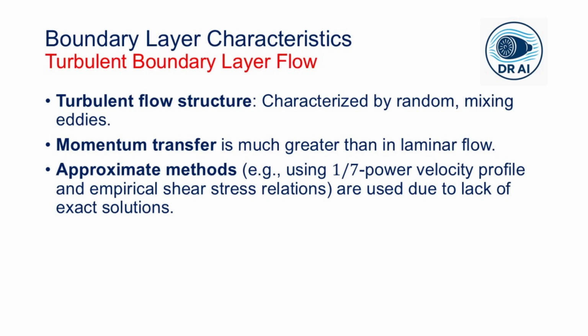Fluid particles moving towards the plate carry excess momentum from regions of higher velocity. Particles moving away from the plate gain momentum from the fluid. So this random cross-stream transport extracts momentum from the flow much more efficiently than molecular diffusion alone.